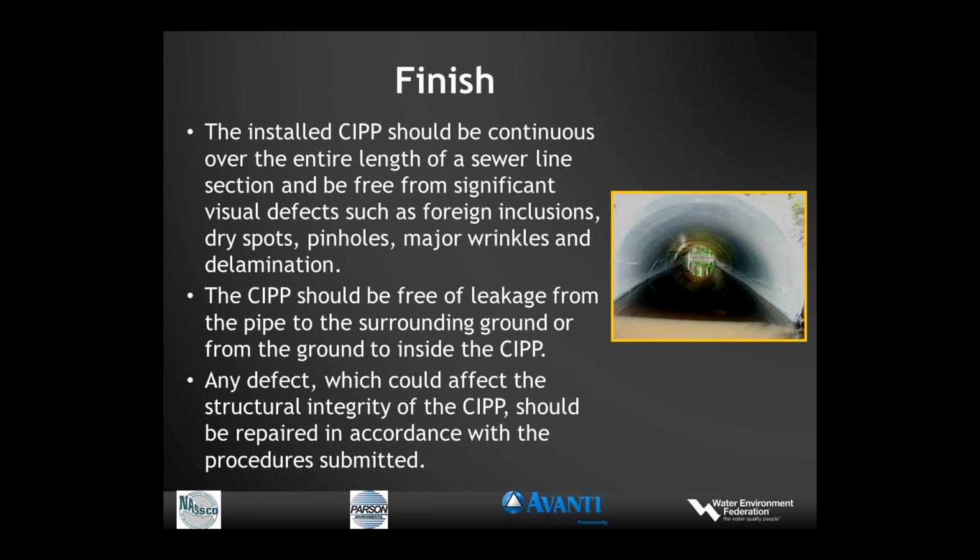You see on the right there a photograph of a completed culvert CIPP. You're looking clear through this one from end to end. And at about 9 o'clock and maybe 4 o'clock, you can see some minor defects, minor wrinkling, which are really nothing. This is very common in cured-in-place pipe. Very minor defects like this are to be expected and are not a problem. So that would fall into that first category we talked about a few slides ago.